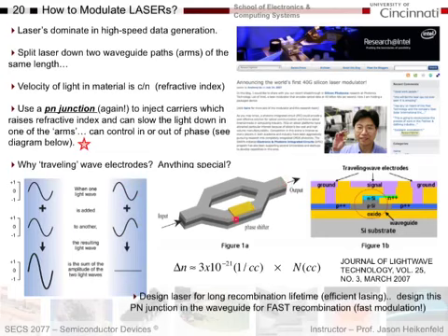So I can modulate this diode very quickly in terms of changing its refractive index to turn the output into 0s and 1s, if I were looking at an output pulse coming out like this, where I have 1, 0, 1, 0, 0, 1, etc. So I could generate an optical pulse by feeding that same data in terms of voltages into this PN junction here. If you make this long enough, you don't need a huge change in refractive index, and if you want to calculate how the refractive index changes as a function of doping or injected carriers, this equation allows you to do that.